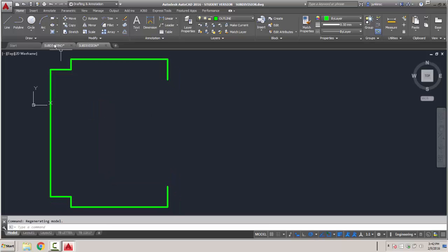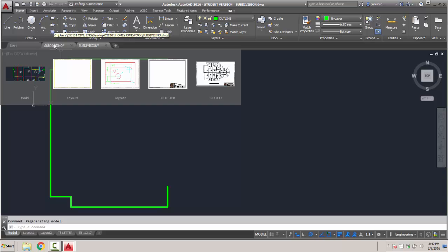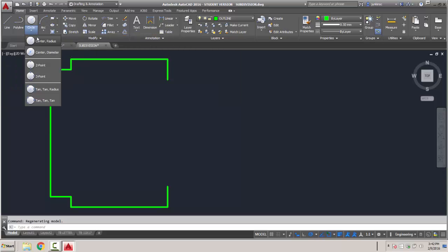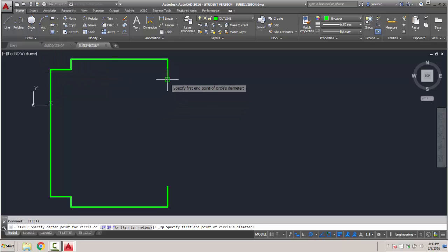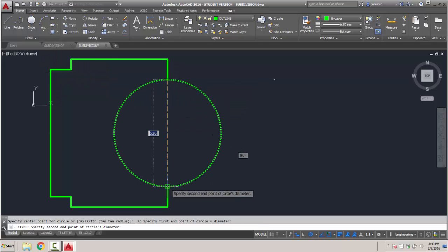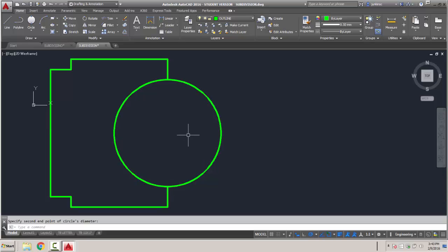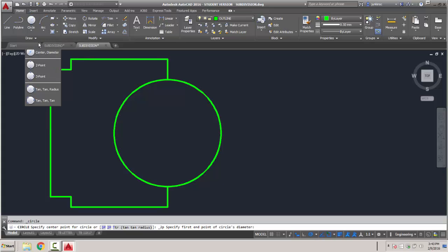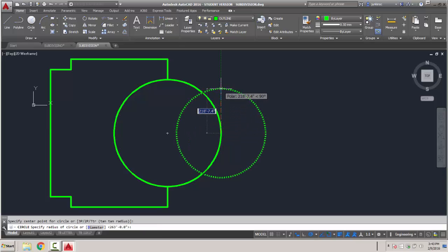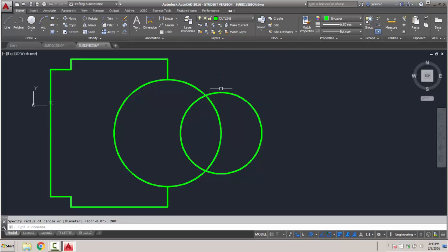Now we're going to take our circle tool. If you look in the book, it tells you to use your 2-point circle tool. You're going to grab a point right here and a point right here. If I right click, then it wants us to do a circle by center. So we change it back to circle by center. Left click, and we're going straight up a distance of, it's a 400 foot diameter circle, so we're going to go 200 feet. Foot mark.